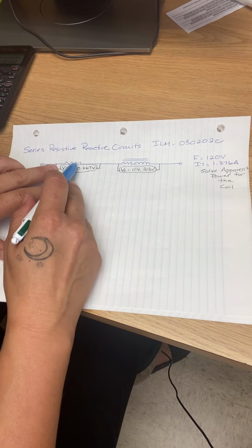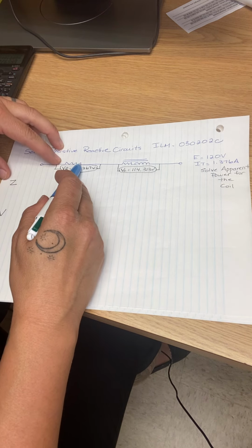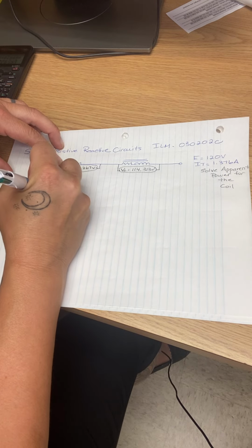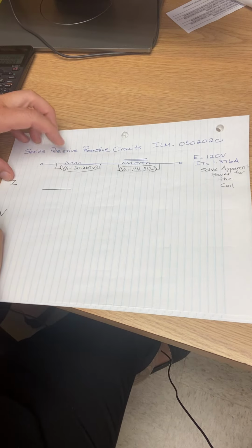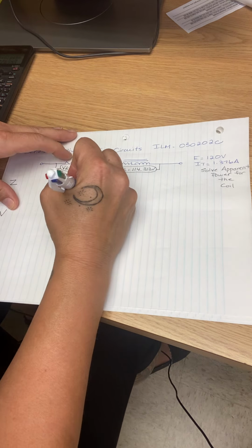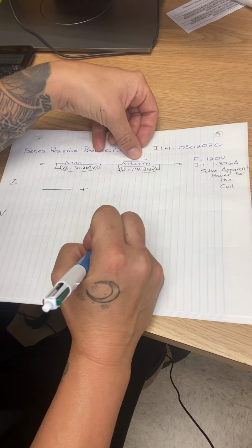Okay, so an impedance triangle for a resistive load, for example, a lamp. An impedance triangle for that lamp is just a straight line. An in-phase load, meaning that current and voltage are rising and falling at the same rate. So whatever value of impedance, it would be found at 0 degrees. And then I'm going to add that to a coil.